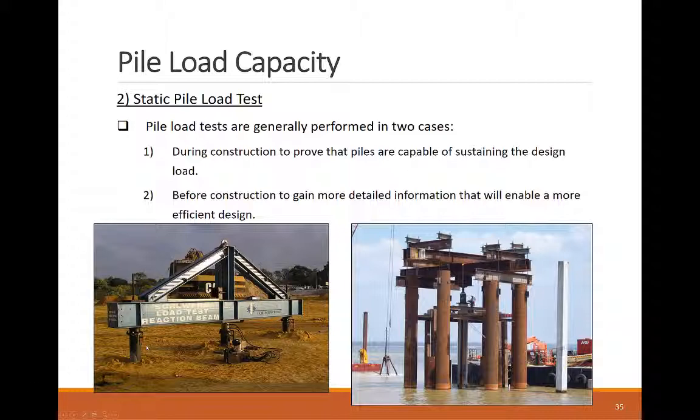This test is done by constructing tension piles around the target pile and assembling a load frame on the pile head. A hydraulic jack applies the load between the frame and the test pile to impose the tension load. The frame is pulled down in place with the help of the tension piles, which obtain the resistance from the soil friction.